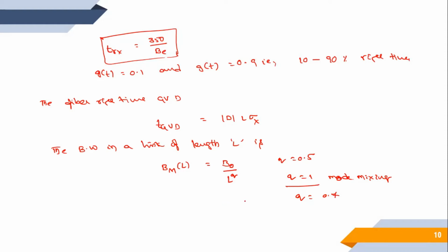Okay, and you can express this bandwidth in a link as 1/Bm = (Σ from n = 1 to N of (1/Bn)^(1/Q))^Q. So this is another expression that is proposed for bandwidth, based on curve fitting of experimental data. And here Bn is the bandwidth of the nth fiber section. If I have multiple sections of fiber, Bn is the nth fiber section bandwidth.